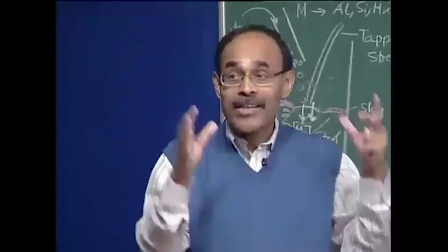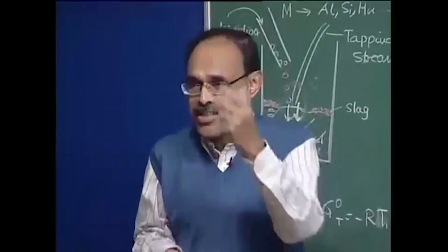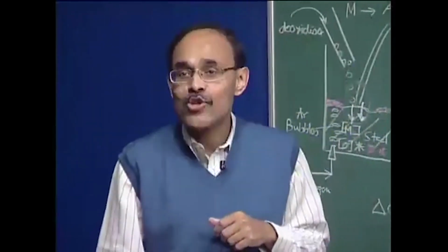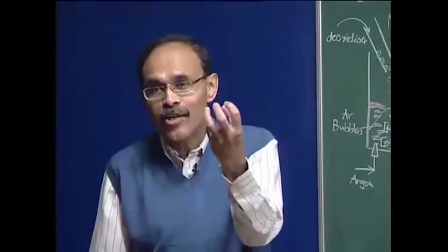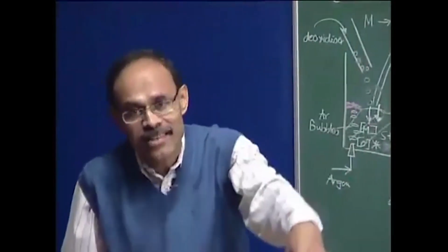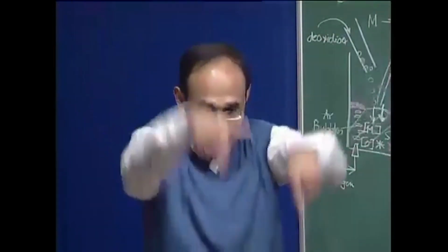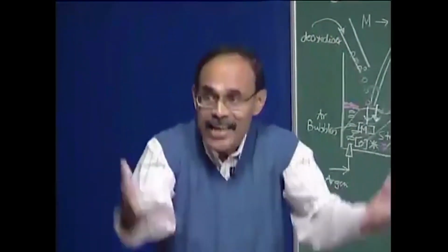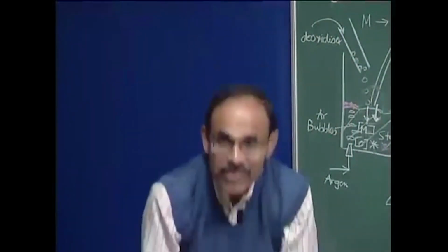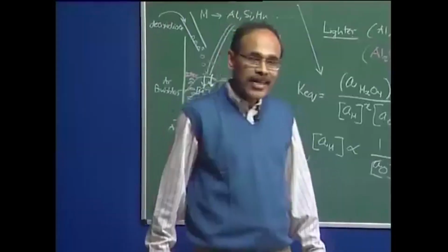And I have shown you that the efficiency of complex deoxidation is going to be greater than that of simple deoxidation. Aluminum by far is the most commonly used deoxidizer element in steel. Deoxidizer elements are basically lighter than steel. So when you make bulk additions into the ladle, we try to target them near the falling stream, where the velocities are highly downward, and this downward flow of steel can take the deoxidizer elements along with it to the subsurface, where subsurface melting and dissolution can take place.